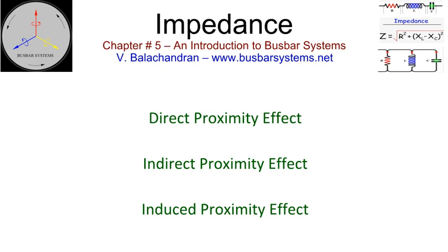Inverse proximity effect. This is the distortion to the current density due to the presence of a neighboring conductor of a different phase carrying current flowing in the opposite direction. Any low and medium voltage connection will have a return conductor, in single-phase connection, or another phase, in three-phase connection, running nearby. In a three-phase circuit, the current in the adjacent phase will run in the same direction, parallel, or the opposite direction, anti-parallel, in a periodic manner resulting in a direct or an inverse proximity effect.